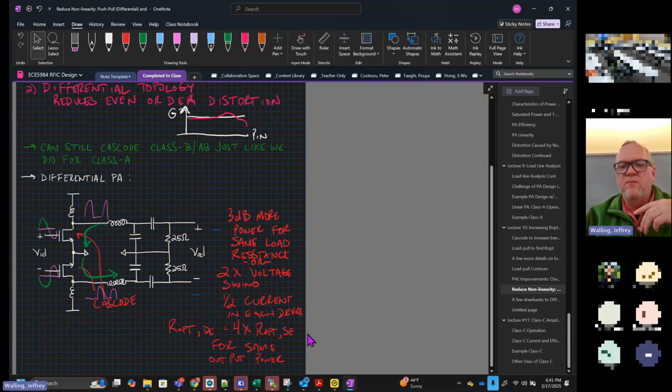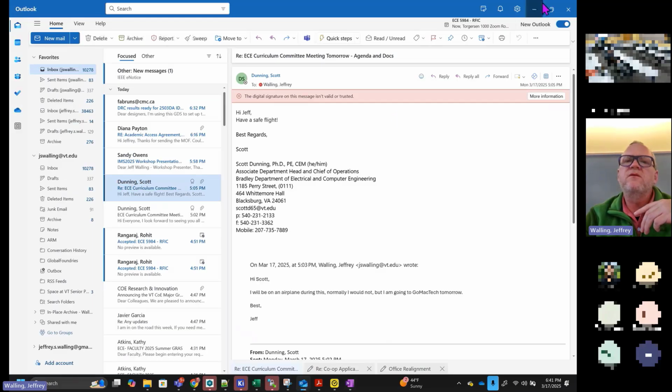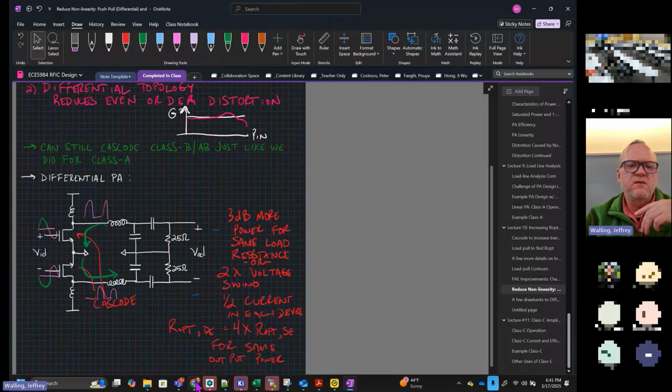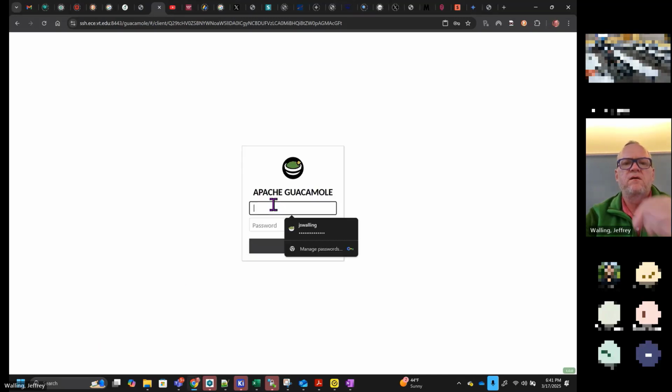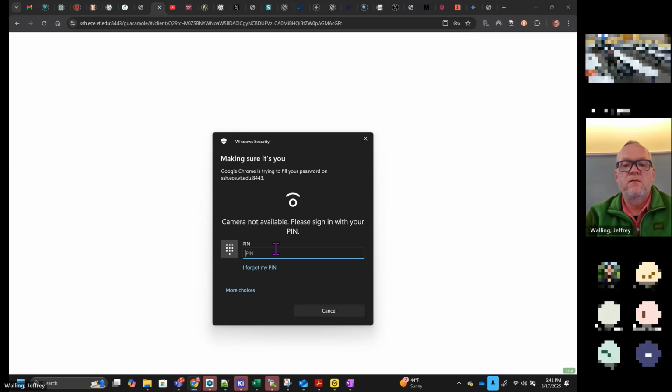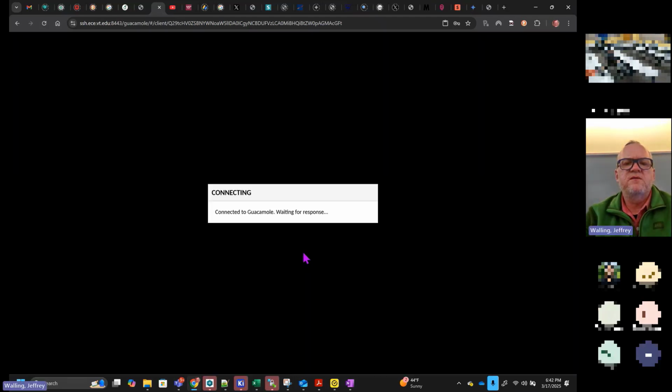And then one other thing I'll try. Some of you have simulations where you might want to show what the transconductance of a device is as you sweep the width of the device. We're going to set that up like we would any other simulation. We'll set width as a variable and sweep width, and then if we run a DC simulation, there is a way that you can, with the calculator, grab the individual parameters of the transistor.